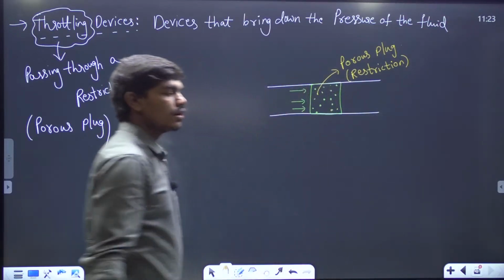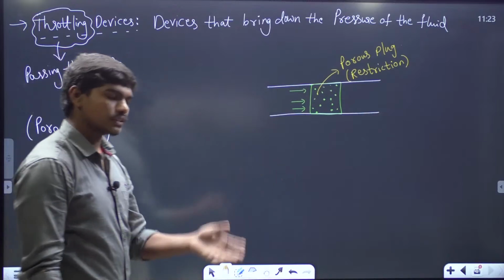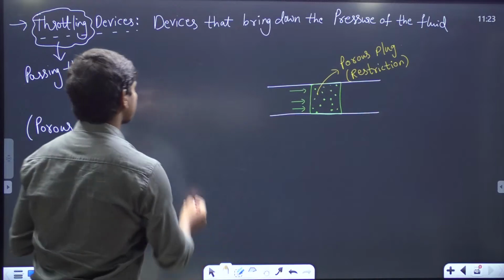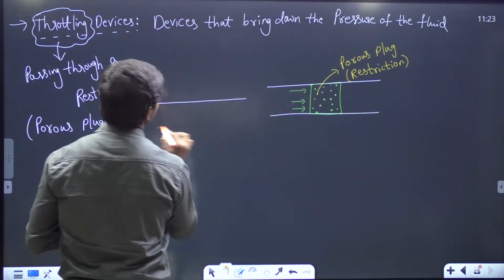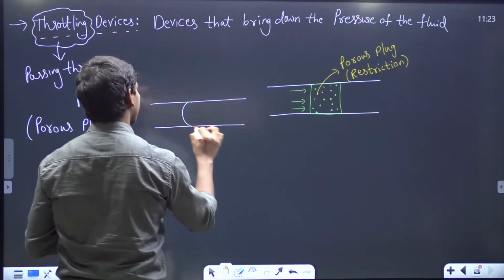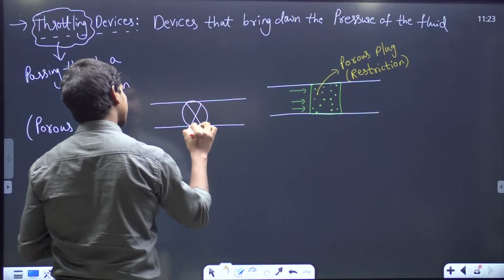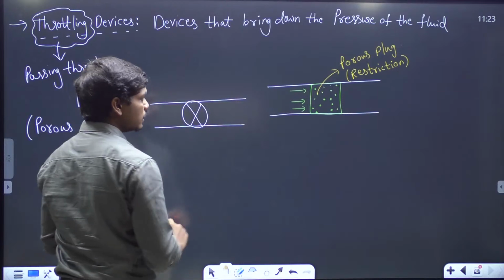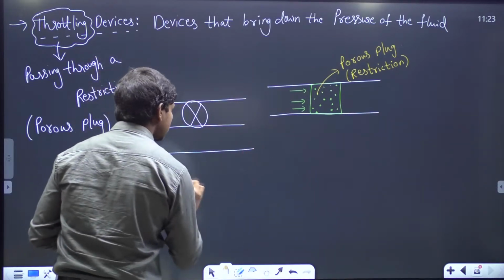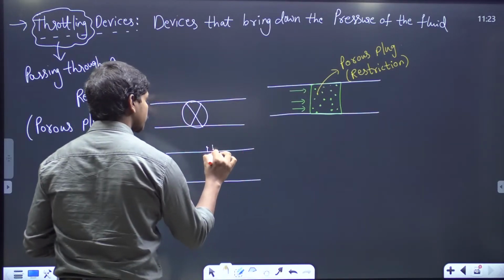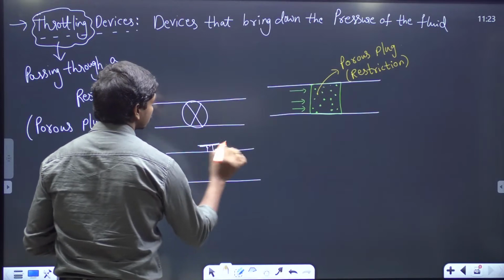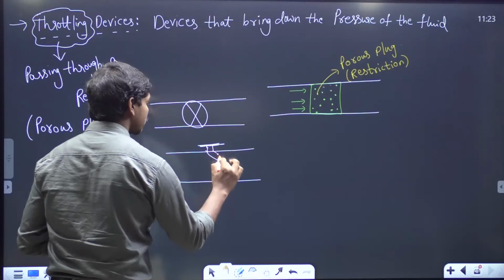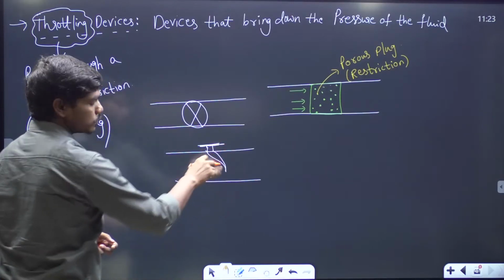In a refrigerator and all these things, basically you have some valves, throttling valves. So generally a throttling valve is denoted by this symbol, like this, which is basically the valve that you see available to rotate. If you look at the inner side, if you rotate this, the restriction that is available here will open to some extent.